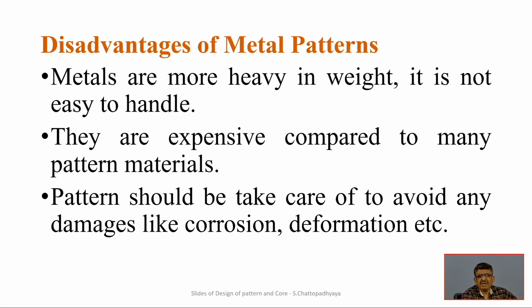Metals are heavier in weight, it is not easy to handle. If the workers feel a lot of pain in order to handle, their productivity will come down. Productivity is a very important thing. Productivity will determine the cost of the product, and because of the strenuous handling, definitely productivity will be less. And they are expensive compared to many pattern materials.